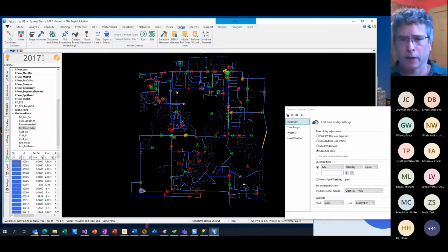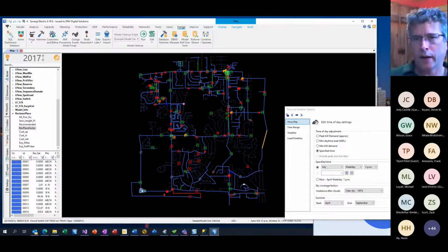And it's pretty handy if you're troubleshooting something from your perspective. So you've got an area that you're looking at voltage problems or whatever. If you run the obfuscate tool, it's going to give the section names, it's going to make them much more clean. It'll start from the first section and just number them. So you can use that to come up with shorter section IDs while you're working on the problem that you're working on.